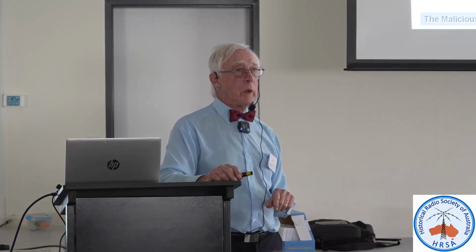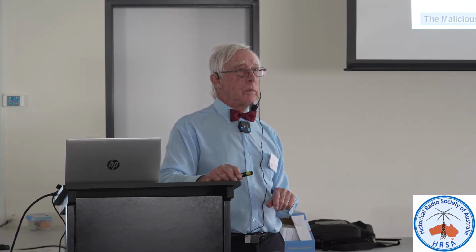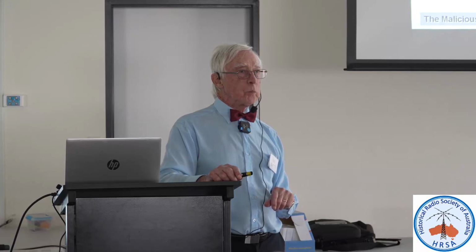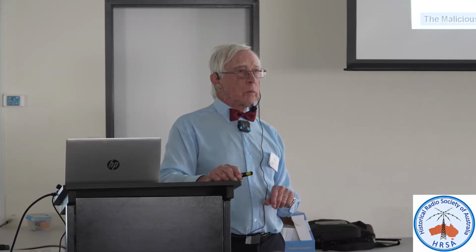The Astor GMs were in that transition phase where they went from all octal to part octal, part miniature, to all miniature over their production life. So you find slightly different circuits, different valve bases and that sort of stuff. So yeah, it pays to pay attention, I guess, when you're working on them to get the right information.